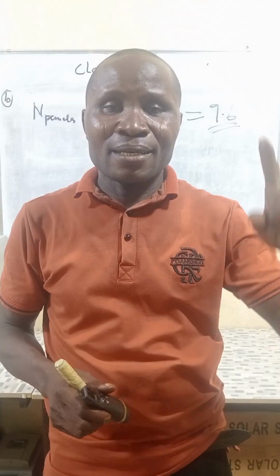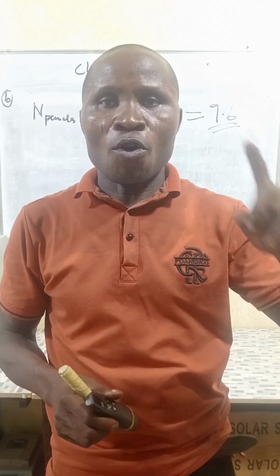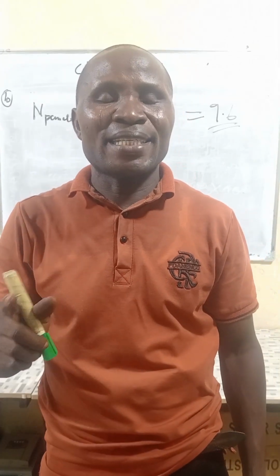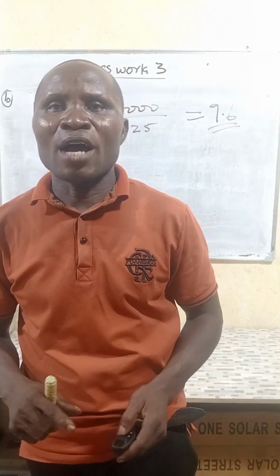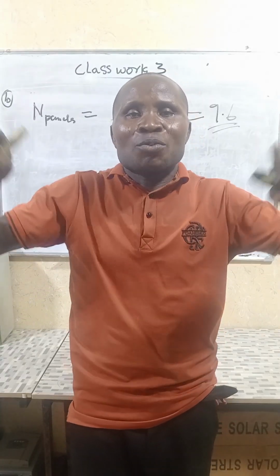Under standard temperature condition, we need 10 pieces of 625 watts solar panel for this installation. But here, we have almost half of the irradiance. That is where the irradiance is put into consideration. Putting the irradiance into consideration is very important, because sometimes what you have from the manufacturer is not what you have outside in the atmospheric irradiance.